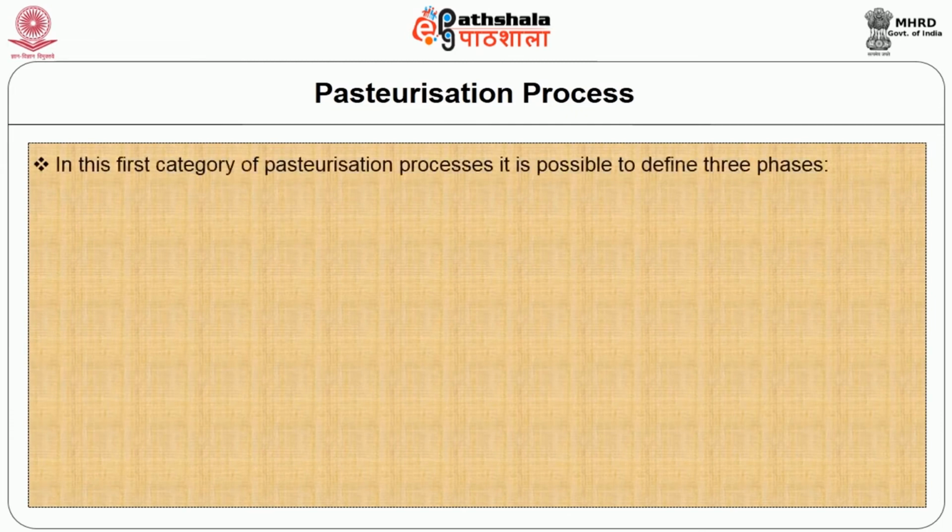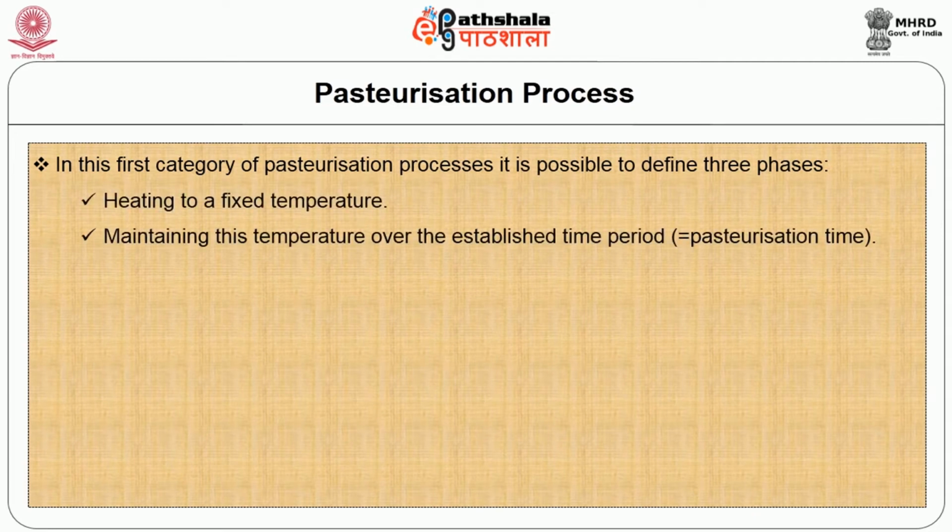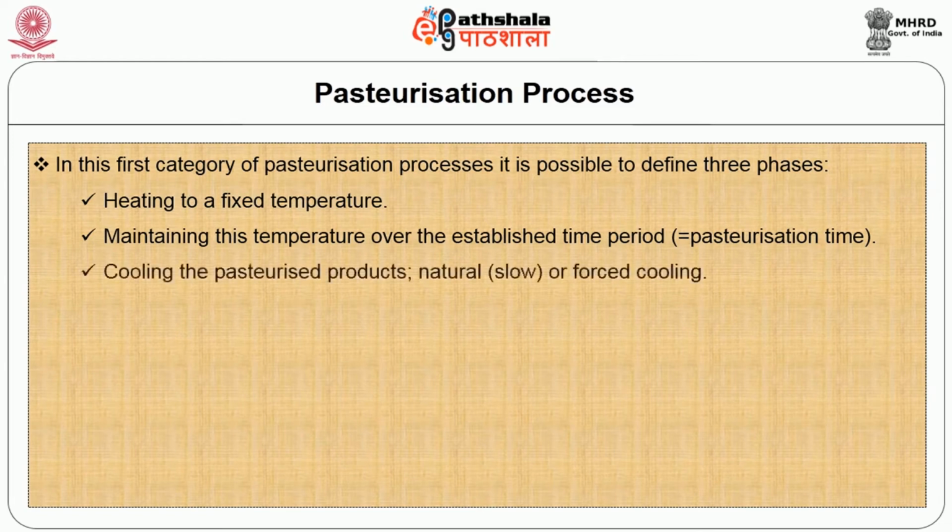In the first category of pasteurization process, it is possible to define three phases: heating to a fixed temperature, maintaining this temperature over the established time period, and cooling the pasteurized product naturally or by forced cooling.